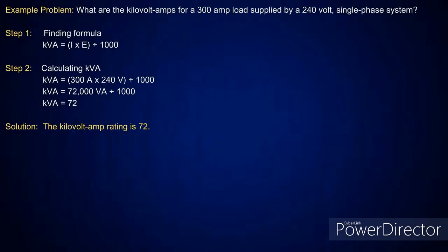All right? Now, looky here. Now I want to find the kilovolt amp rating. Okay? I got 300 amps load, 240 volt single phase. Just multiply everything together and divide it by what? 1,000.